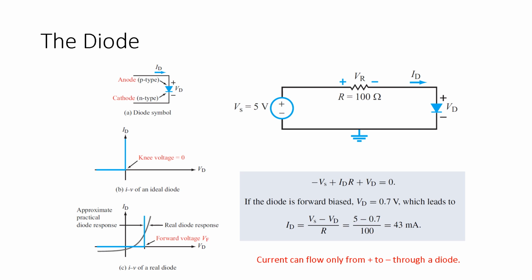If we look at the circuit up at the top here, we have a 5-volt power supply, we have a 100-ohm resistor, and then we have a little diode over there. And so, presuming that this diode is forward biased, the way I think of it is correctly oriented for simple circuits like this. If it's backwards, it's incorrectly oriented, and a reverse biased diode is not going to let current flow through. So forward biased, good; reverse biased, not good in this case. That's how I remember it simply. It's not technically correct, but that's a good way to start.